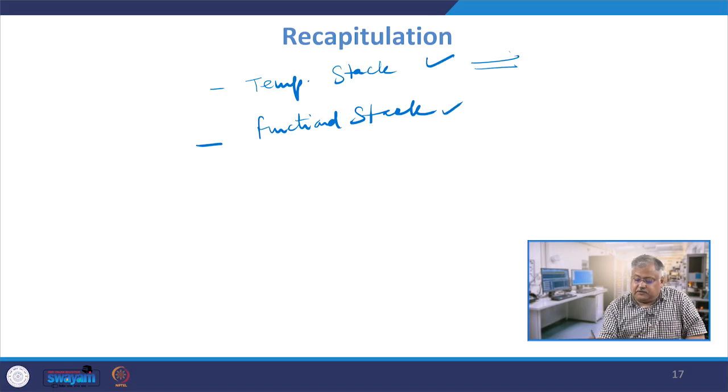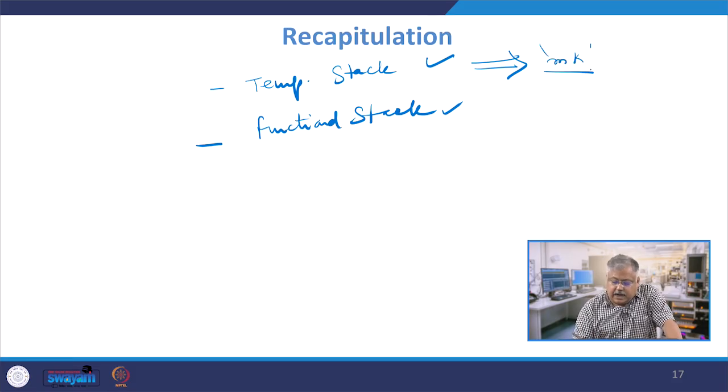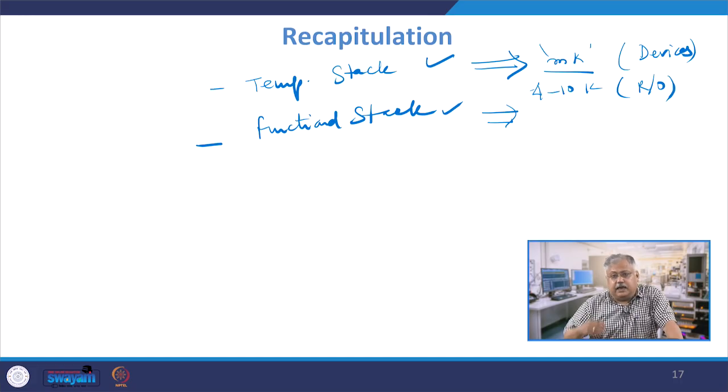We also saw, when discussing this, that our qubits are placed at millikelvin. In the functional stack, the lowest layer is the devices, which is where you keep your devices. From around 4 to 10 Kelvin is where you keep your readout circuitry and other parts, and anything above that is responsible for keeping the other parts of the system. So the devices are at millikelvin, then all your multiplexing and routing methodologies are at 10 Kelvin, and anything above that is the software, control, and application domain.